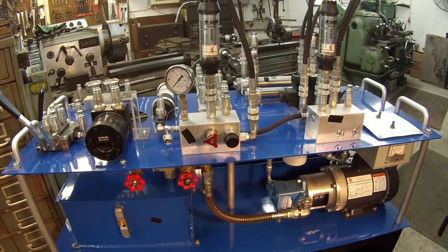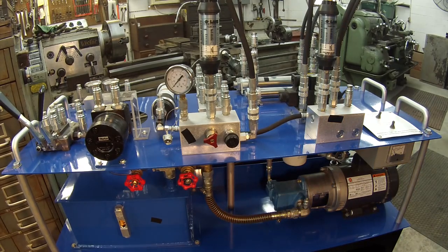Alright, I hope this first session, that's the end of session 1, was beneficial to you guys. One of the things I really want you to walk away with, a takeaway from this particular video, is pressure is force and flow is speed. If you have something in your system that's slowing down, that is a result of your losing flow somewhere. So these flow meters right here, when we get into the troubleshooting part, you'll see how essential those items are. Again, that's a flow meter, that's a pressure gauge, and we went over all the other components.